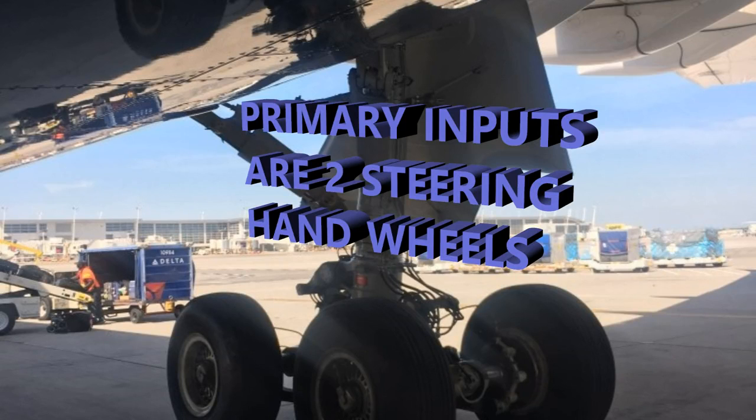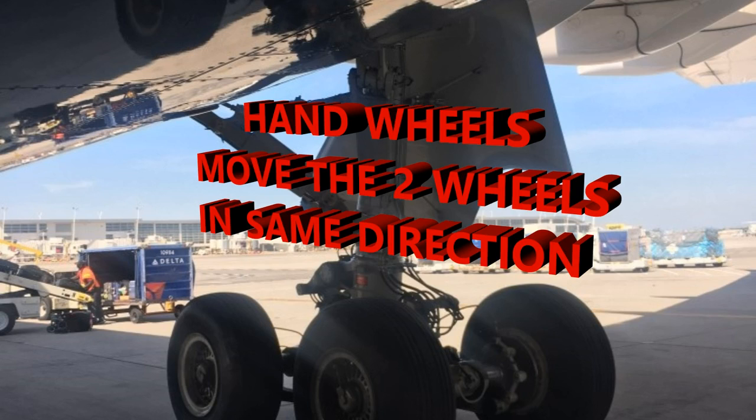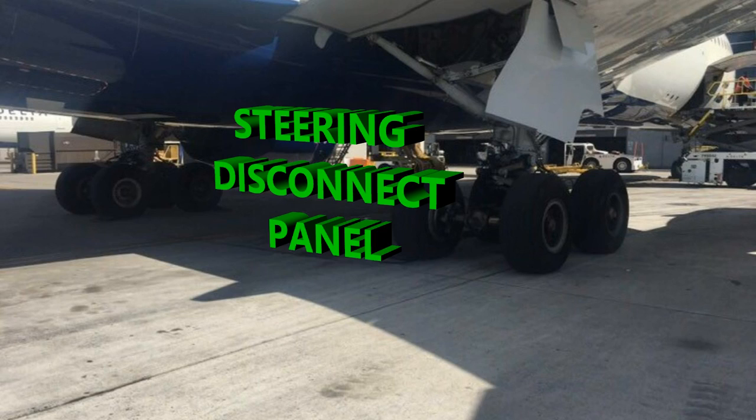We're talking about the steering of the nose landing gear. There are different inputs you can have. The first, and the more primary, is your inputs from the steering hand wheels. There are 2 of those. You can also control it by autopilot and the rudder pedal commands. The hand wheels move the 2 wheels in the same direction. And there's also the steering disconnect panel.